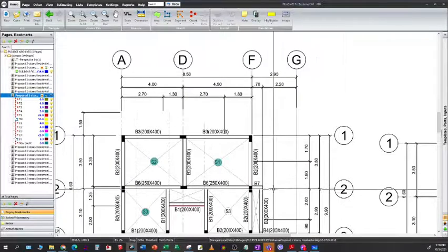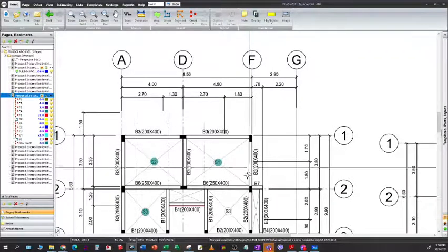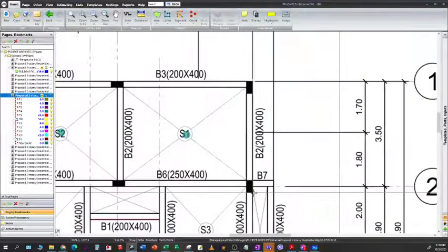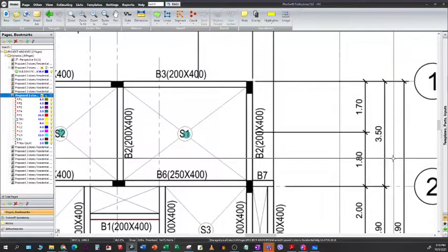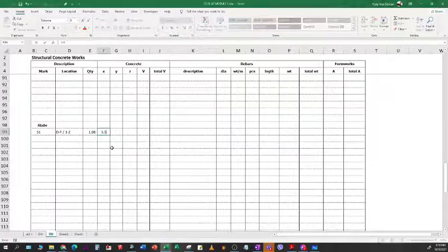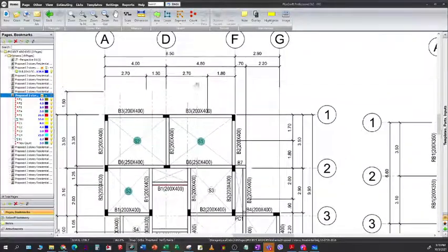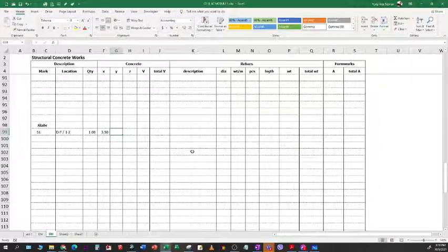I will use the dimensions having the allowance, because the dimensions are not center to center or clear span to clear span, but the exterior face of each beam. So this one, 3.5, is coming from here to the other end, and then 4.5 on the other side. Then for the Z dimension, let's take this one to be the thickness of the slab.